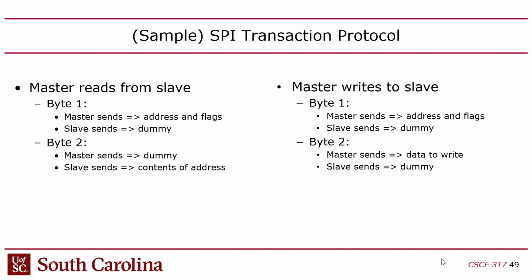You guys with me? You might be thinking, this seems like a hacky way to handle this. You have this capability of SPI of doing exchanges, but you never really do a true exchange. It's always just one side or the other sending meaningful data, and the other side sending back zeros. So why always do exchanges? I don't know. That's just something you have to do for SPI.